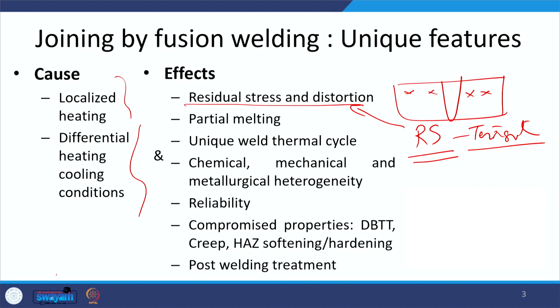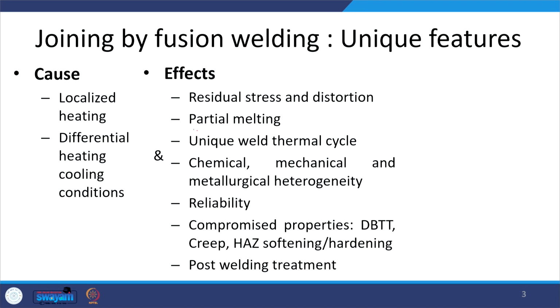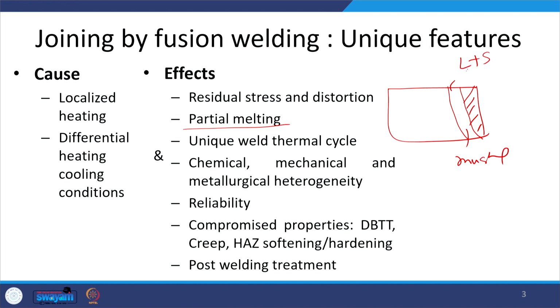Okay. Another thing that is experienced is partial melting. When surfaces are brought to the molten state, this zone has been melted. But next to that area there will be a mushy zone, especially in the case of alloys, where we will have both liquid and solid. So, it causes partial melting, especially in alloys having a wider solidification temperature range, and this in turn promotes liquefaction cracking.